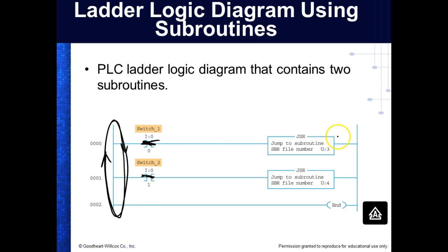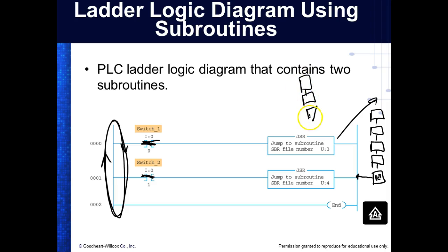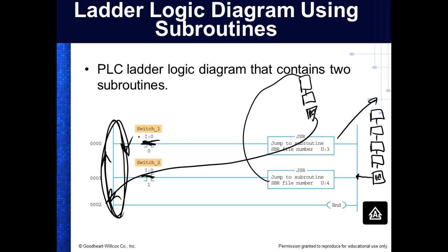But what we're doing here in ladder 0, we're sending it off to a subroutine, and that subroutine comes flying down through here, and then the last one is a what? Return, and they're calling it RET. Where would it come back to? It's going to come back to right there. And then it's going to do what? It's going to go out here and run a different subroutine, which is somewhere out here, right? Then this is going to be an RTE. So this guy's going to call this guy, run it, see the return. Where's it going to come back to? Line 2. Line 2 tells it to do what? Scan, and then it'll just redo the scan.